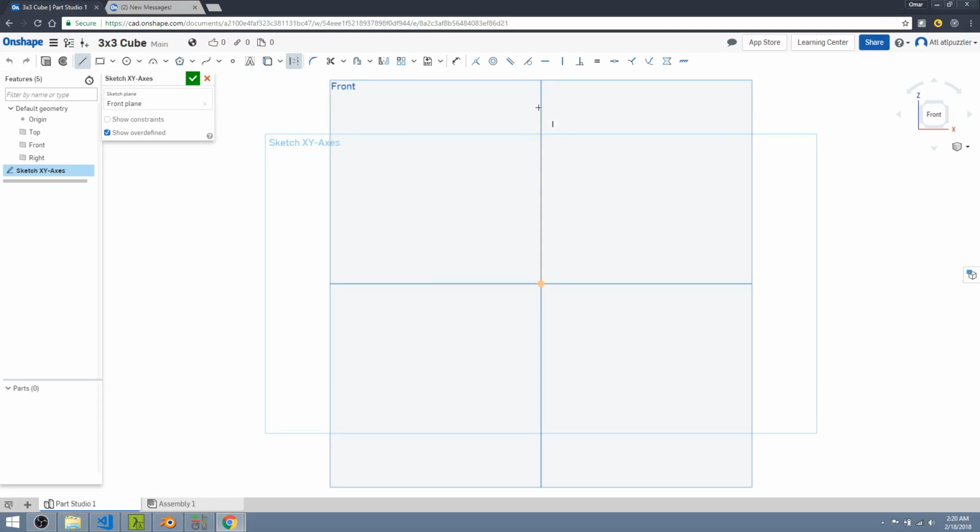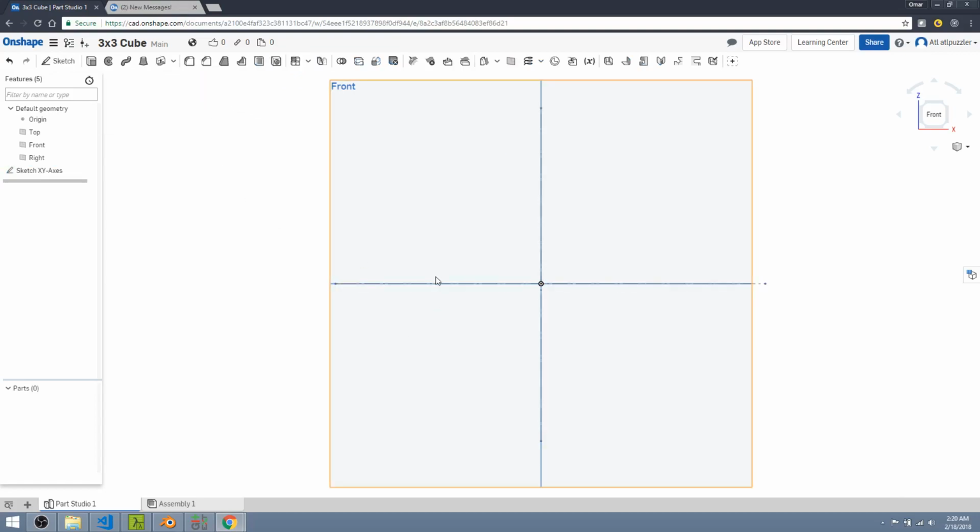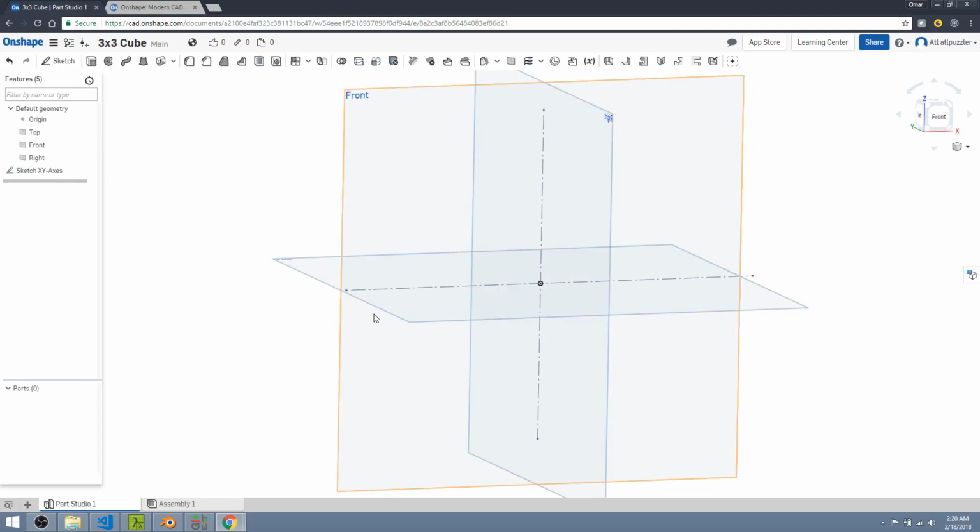Anyways, I'm going to hover here vertically, and you see it created a dotted orange line that goes through the center. I'm going to single click and drag at the bottom here, and single click again and created a vertical line. And then I'm going to press escape to stop drawing. I'm going to click this line again, and click again, then press escape. Actually, I forgot to click the construction line, so I'm going to single click it and click here again, and there you go. And I'm going to click OK, and now we have X and Y axes that we can use.